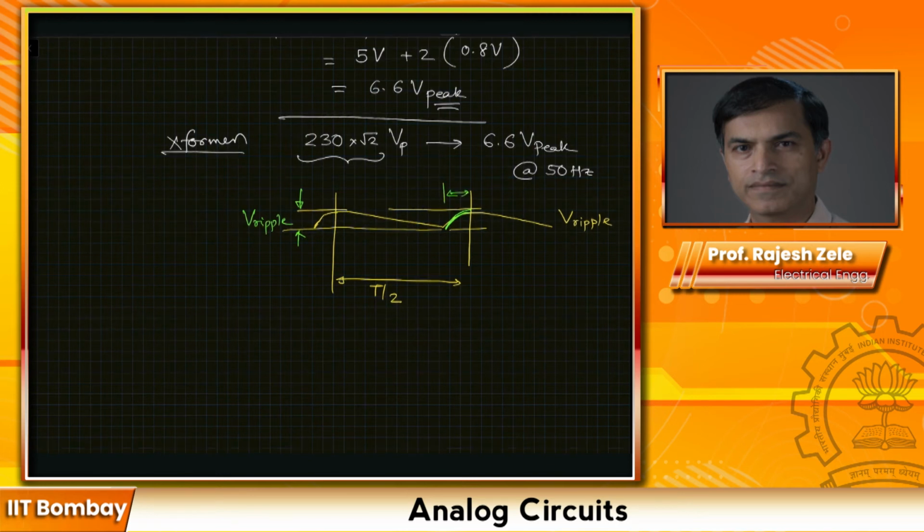We are going to say, let's ignore this portion of the curve for now. So we get an equation, dV out by dt is equal to I load divided by the capacitor C. Just for your understanding, we are only looking at a model that looks as simplistic as this.